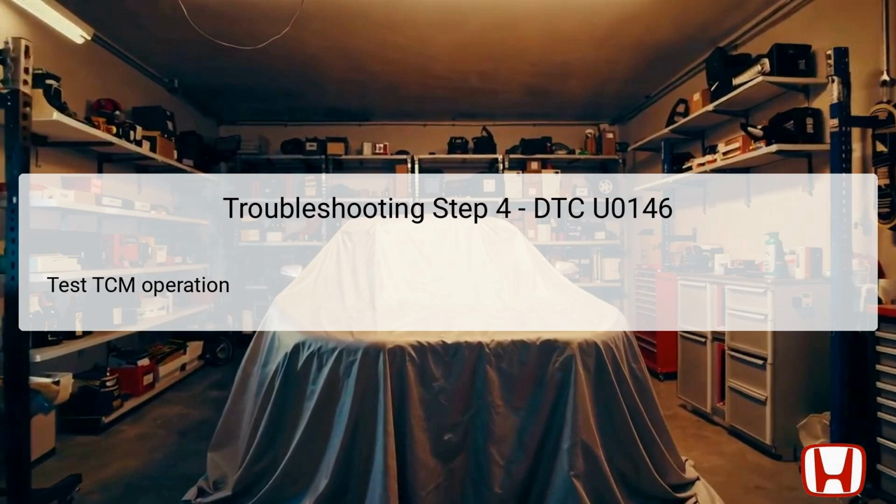After verifying the FCAN circuitry and checking the CAN gateway, the integrity and functionality of the TCM must be confirmed. This includes ensuring that the module is receiving accurate signals from the CAN gateway and that it is capable of processing those signals effectively. Diagnostic equipment may be utilized to assess the TCM's response to specific inputs and monitor its real-time performance metrics.